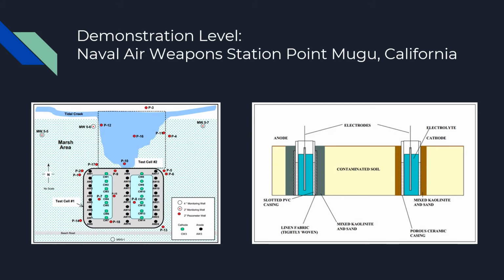Observation. The VOC data indicated an increase of vinyl chloride in some wells. This increase in contamination was mainly due to the dehalogenation process of PCE and TCE during electrokinetic remediation. The site characteristic that was primarily responsible for the poor performance of the remediation treatment was the presence of high chloride concentrations in the soil. The chloride ions retard the development of the pH front and in turn slow down the process of contaminant transport towards the electrodes. The site conditions thus proved to be disadvantageous for electrokinetic remediation.